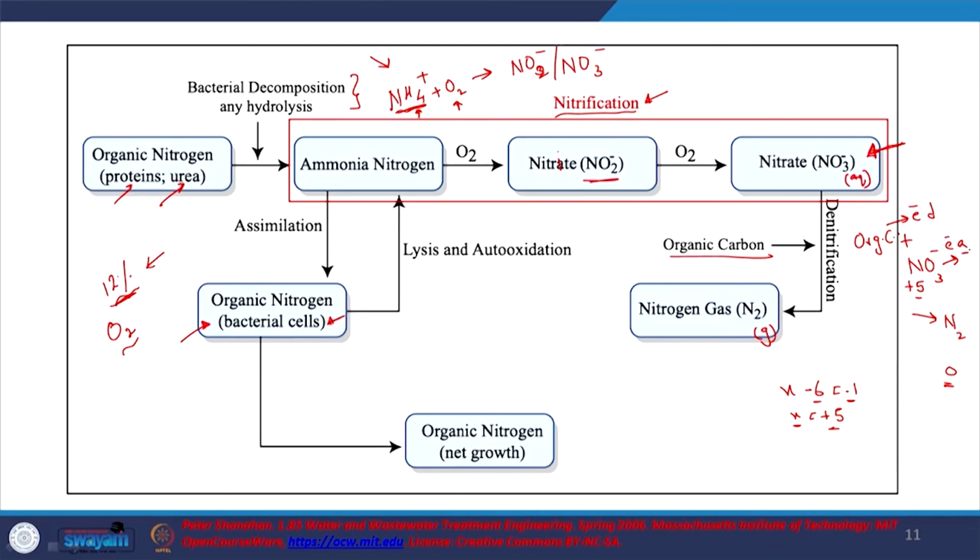One thing to note is that in the usual activated sludge process, where we are degrading the organic content of our waste, oxygen is also the electron acceptor. That is good enough for nitrification. But for denitrification, as you see, NO3 minus is the electron acceptor. So if oxygen is present in the system, denitrification will obviously not take place.